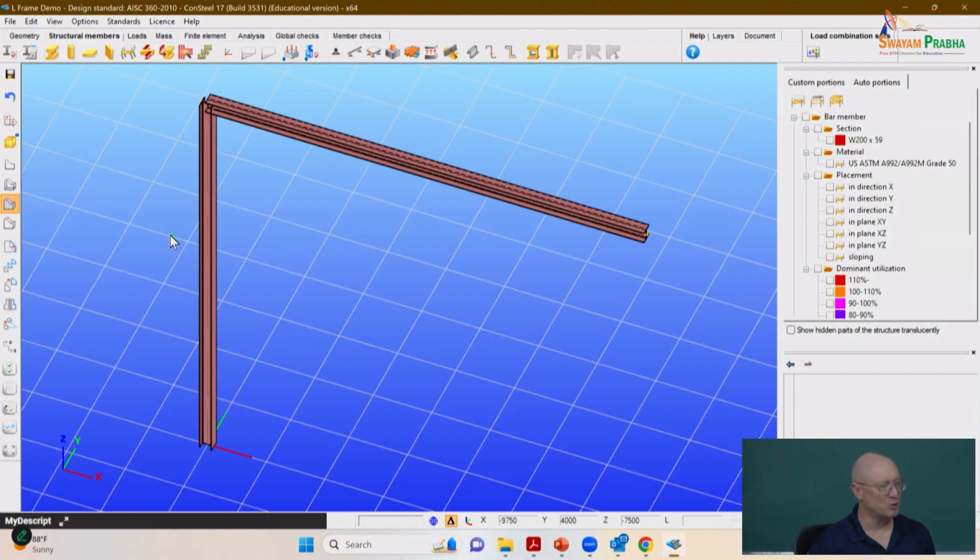By default, it assumes that everything is rigidly connected. Now, when it comes to warping, warping in the beam at the knee joint is not the same as warping in the column. There are some very sophisticated aspects there that only a few people, Nick Trahair in Australia and a number of others, have explored over the years, and they've implemented it.